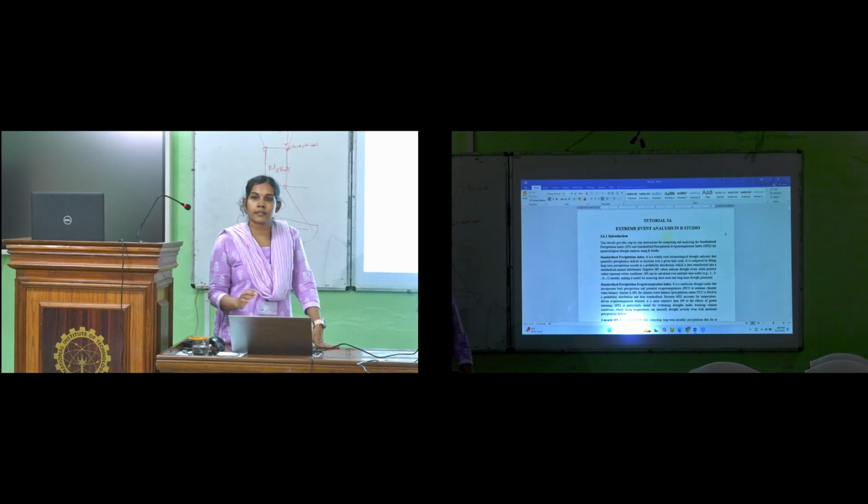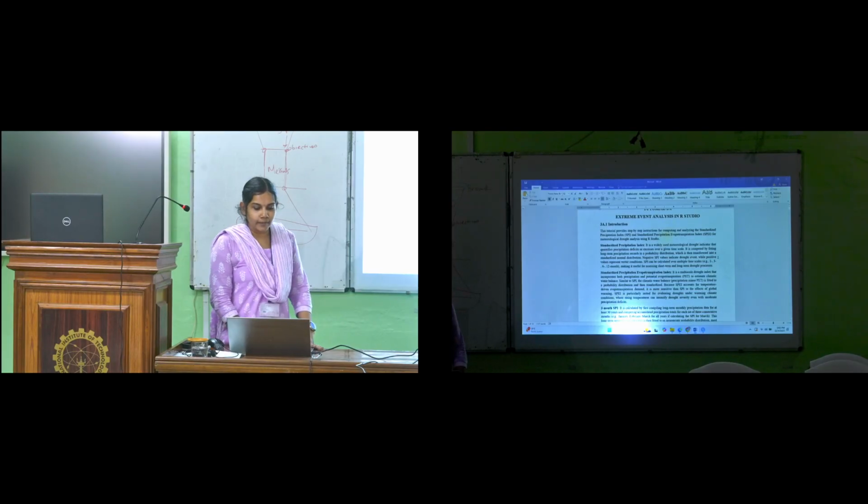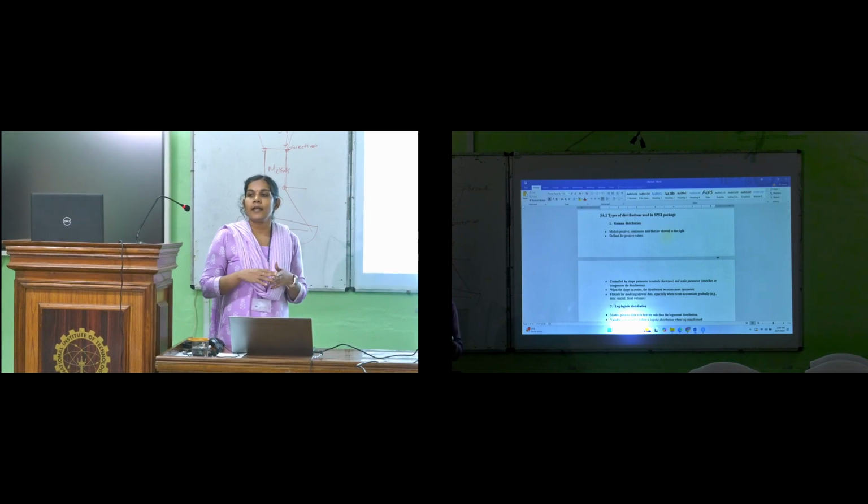In yesterday's class, the definition of drought, different types of drought, the different indices used for the calculation of drought events, and the case studies were already discussed. So I am not explaining that. In RStudio we have one package named SPEI. Using that package, we can analyze meteorological drought. Mainly in the SPEI package, we can analyze both SPI and SPEI.